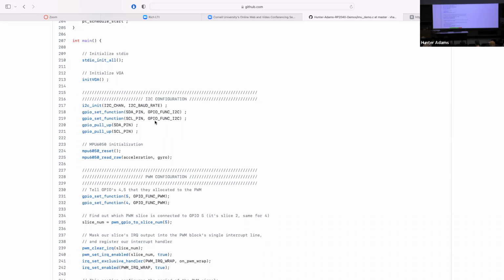It makes the higher pull-up resistors make it more difficult for the I/O pins to change the value of that voltage. So say we have a bus that just rises like this. A higher resistance will cause it to be smoother. Yeah.